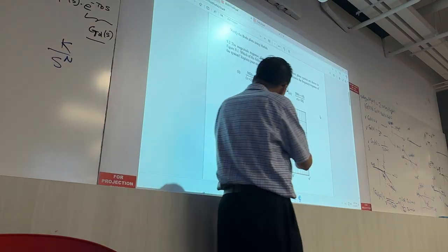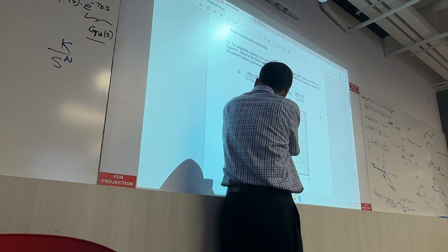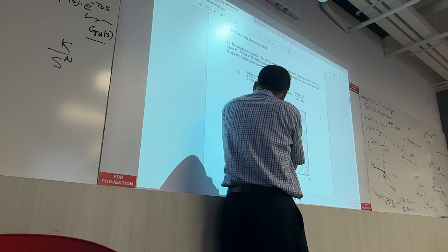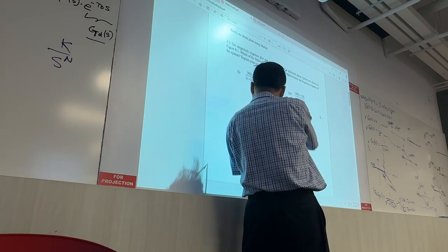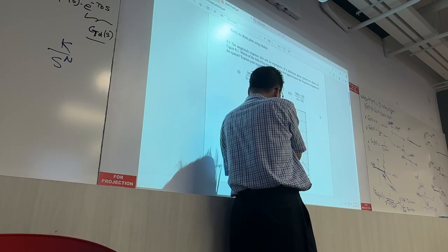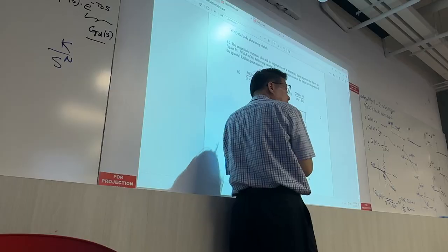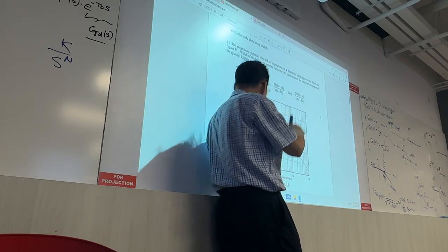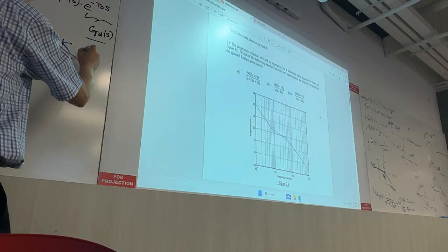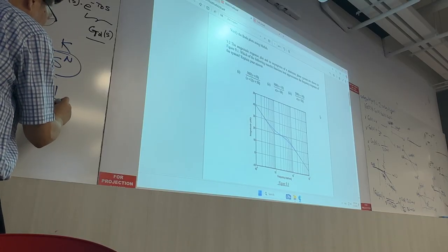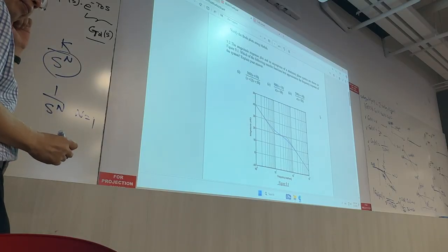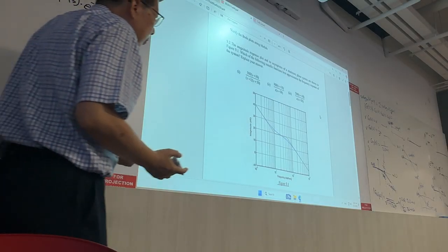Then you look at this Bode plot, and from the left side you can see the feature: in 1 decade, it reduced by 20 decibels, from 40 to 20. So n is equal to 1, it has this 1 over s to the power n with n equal to 1. This is the first confirmation.